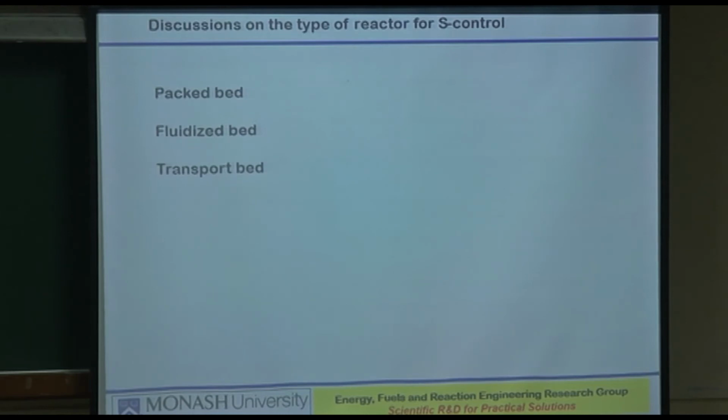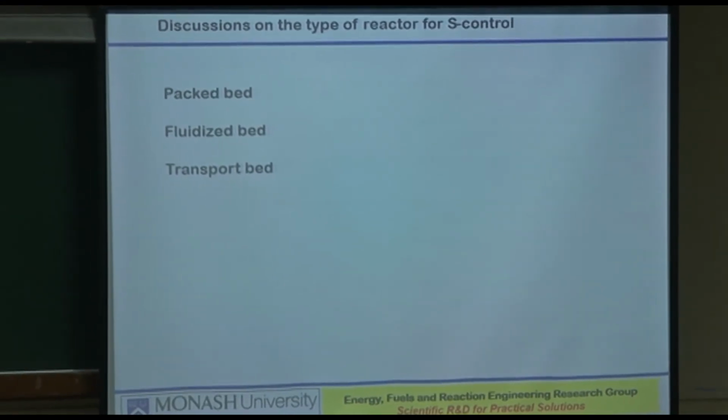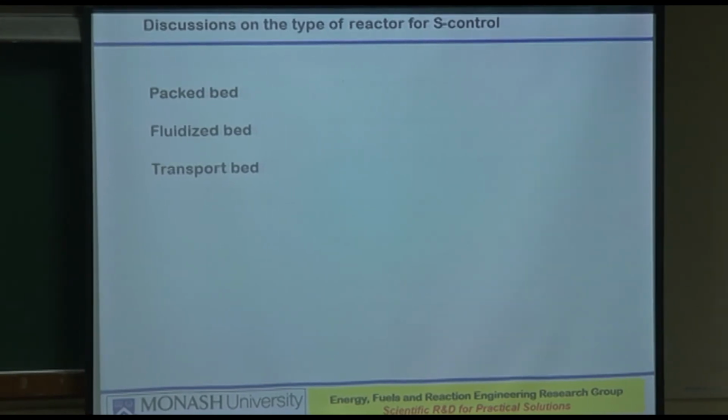Yeah, I think we are getting the answers now. Gas solid contact is another one. So the transport beds definitely will give you much better gas solid contact, almost as good as what you can have from the fluidized bed. But the transport beds will be a little bit more complicated in their design, in the sense that some of the catalyst particles for sulfur control may get completely elutriated from the bed, and you need to bring them back into the bed quickly. Okay, and that's what I think all three of you have been saying.